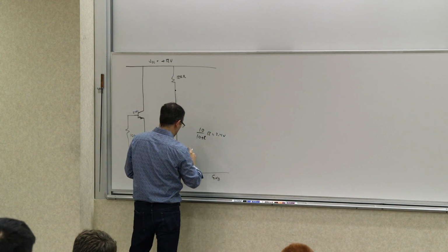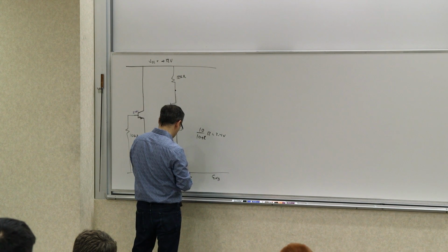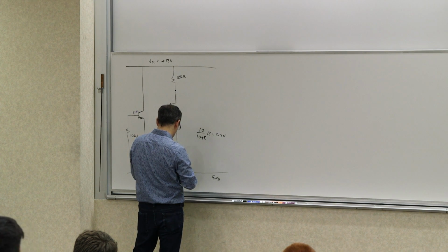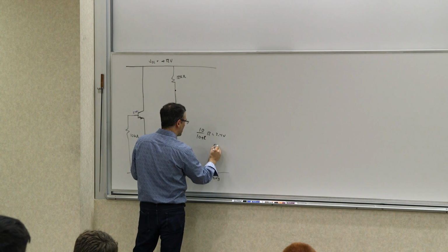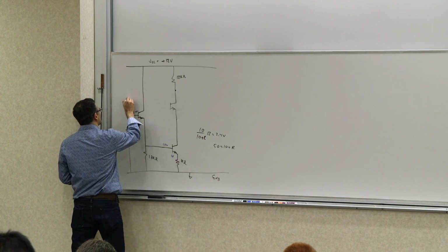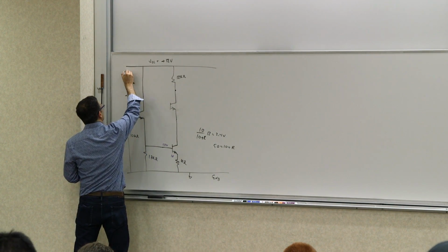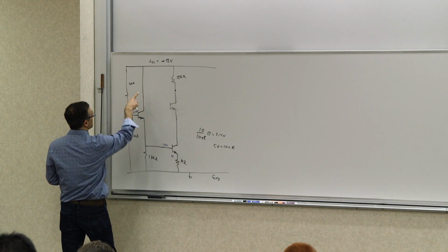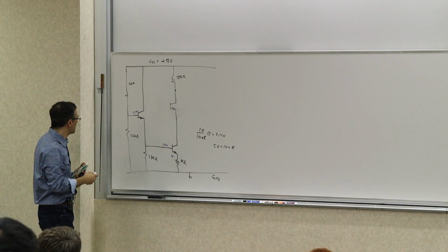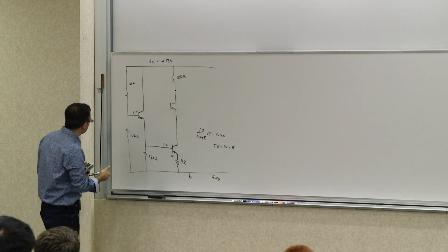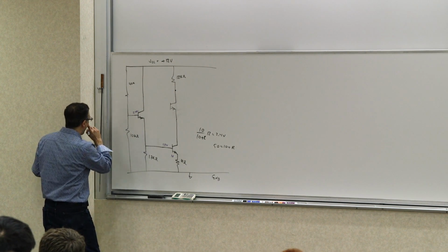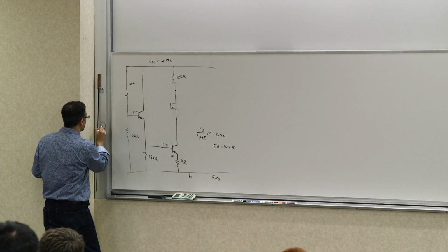So that's going to be 2.4 divided by 12, which is 0.2. 10 divided by 0.2 is 50. So 50 has to be 10 plus R, which basically means R is 40K. So this is going to be a 1/5 division, which would be 2.4 volts, roughly. So it produces the 2.4 volts that I want there. That sets my bias point. But now I have to apply my source, and I'm running out of space. So here's my source.